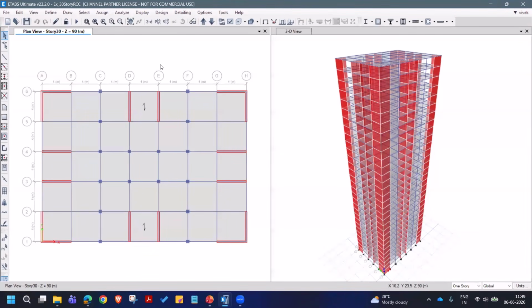And then for the cracked section properties, as per table number 5, it has been given for serviceability and then strength. Although the program can handle both in the same model, for practical purposes, you can have the ULS model with these properties and then a serviceability SLS model for modeling the modifiers separately for the serviceability checks. So I'm showing the model, which is for the strength design.